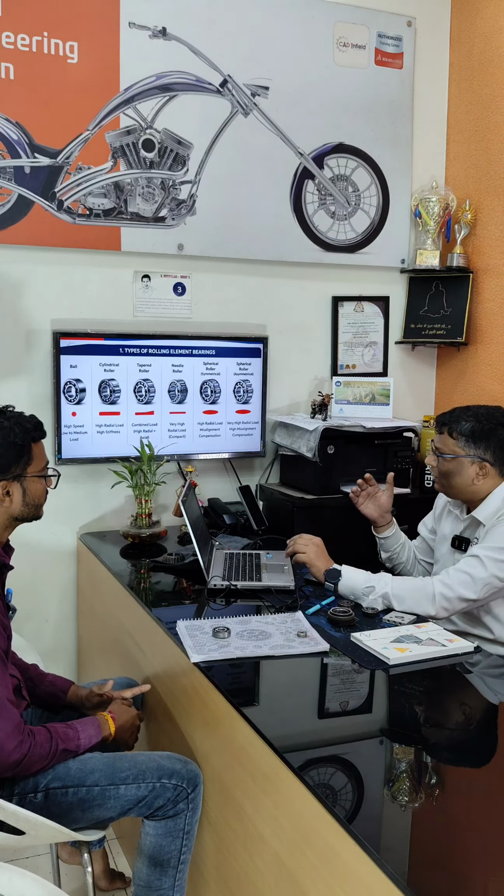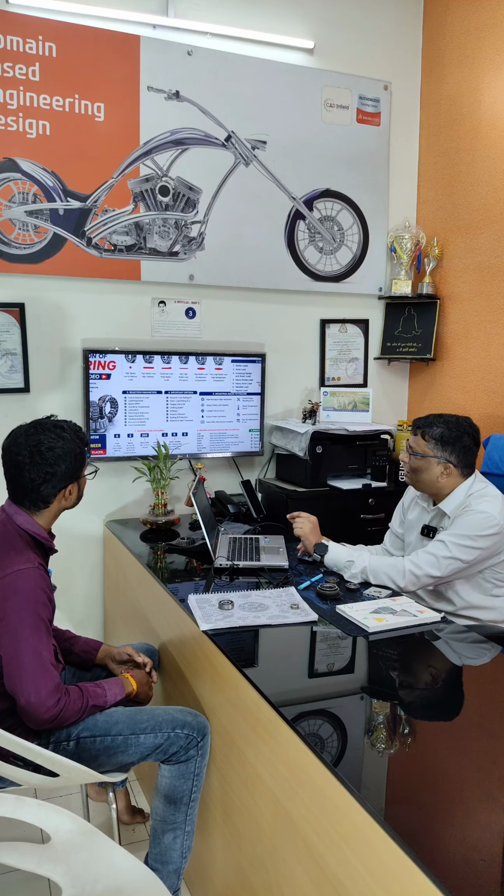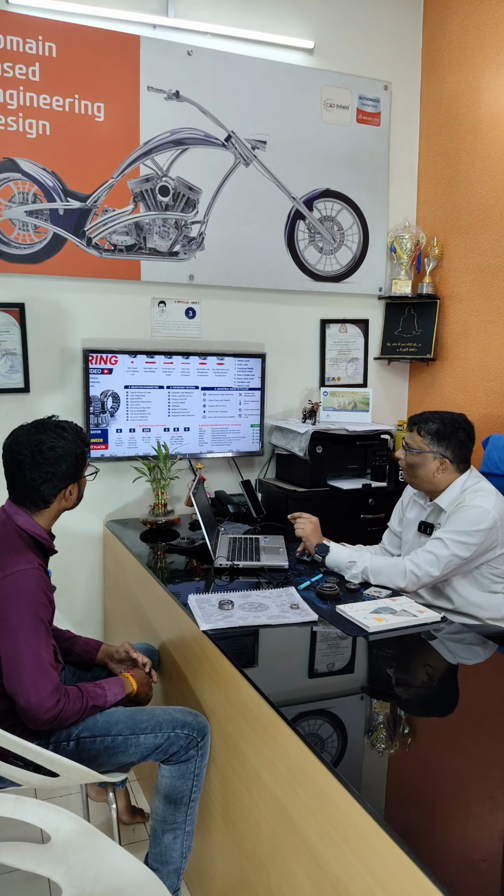I will brief you with a step by step guide so you can understand. First, based on the load, direction and magnitude, you need to select the type of bearing. Second, you need to understand the operating condition: speed requirement, lubrication, mounting.